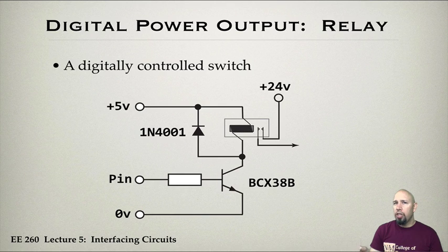That is, if we wanted to use our Arduino to turn on a light bulb, like a 100-watt light bulb, or even higher watt, like stadium lights or something like that. Obviously, those lights are going to take much more current than the Arduino can put out. So we know that a digital signal is like a switch, right? So what we need to do is connect up our digital output to some kind of a switch that can actually handle that kind of current.